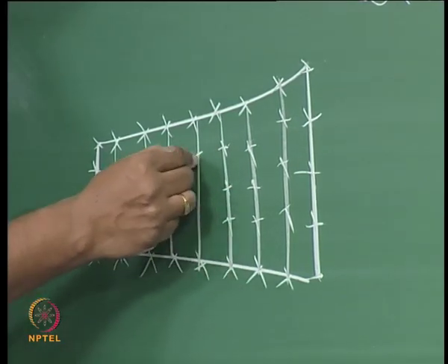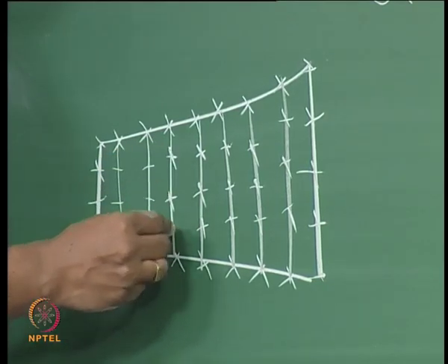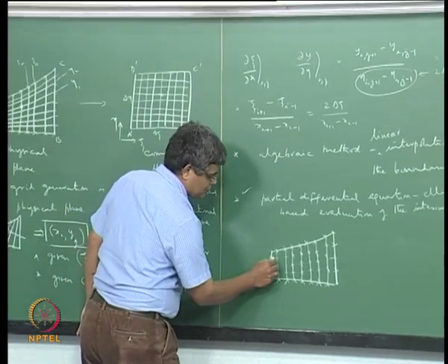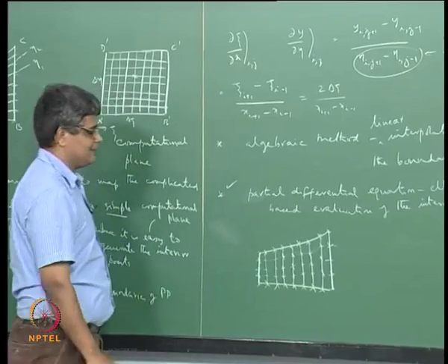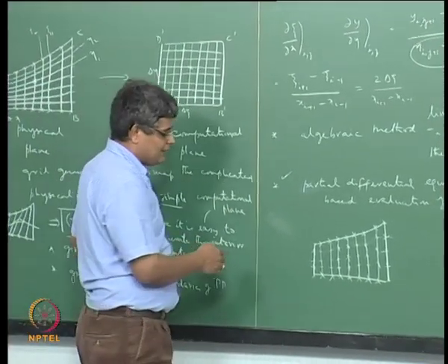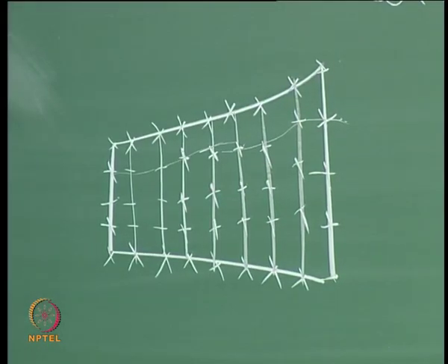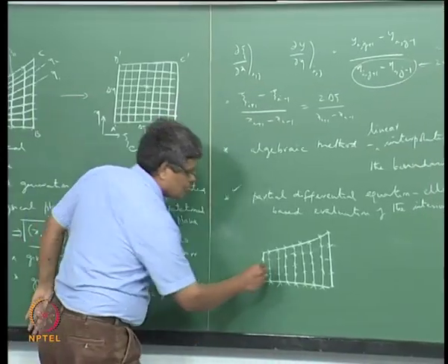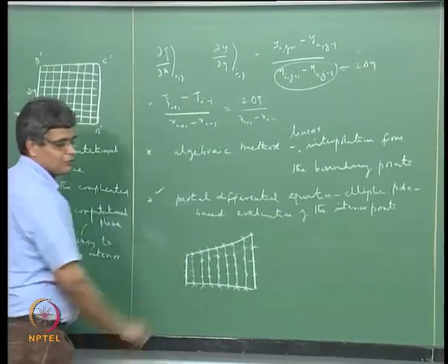So you are not essentially reconstructing any constant psi line and constant eta line like that. It is understood that if you were to join them by a line, that is your constant eta line corresponding to this, but we are not at any point creating a curve which is going through this, because for the evaluation of the matrix it is sufficient to know what the coordinates xi, yi of the interior points are for given boundary points.